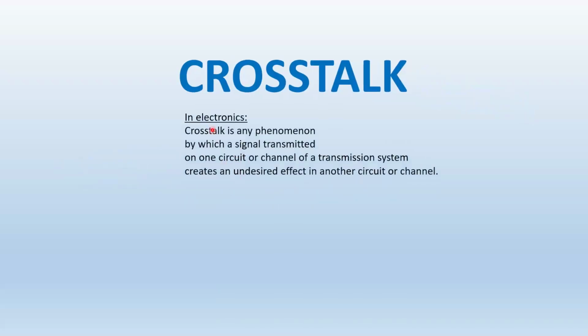All right, so let's see crosstalk. In electronics, crosstalk is any phenomenon by which a signal transmitted on one circuit or channel of a transmission system creates an undesired effect in another circuit or channel, which means one pair signal flowing through one pair is affecting the other signal in the other pair of conductors.